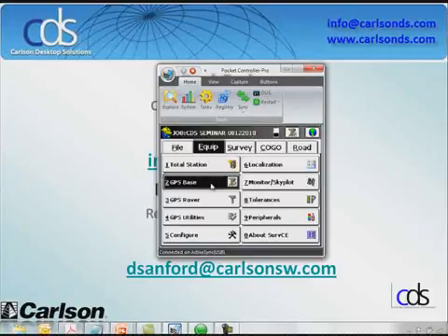Now, again, I'm not going to connect another base. Really no need to. The connection settings for the rover are pretty much the same. The key here is to make sure that my settings match. If I'm using a CMR message type on the base, I want to use CMR on the rover. I don't want an RTCM3 and an RTCM2 trying to communicate. It's just not going to happen. So we verify those settings. The basic procedure is the same here,